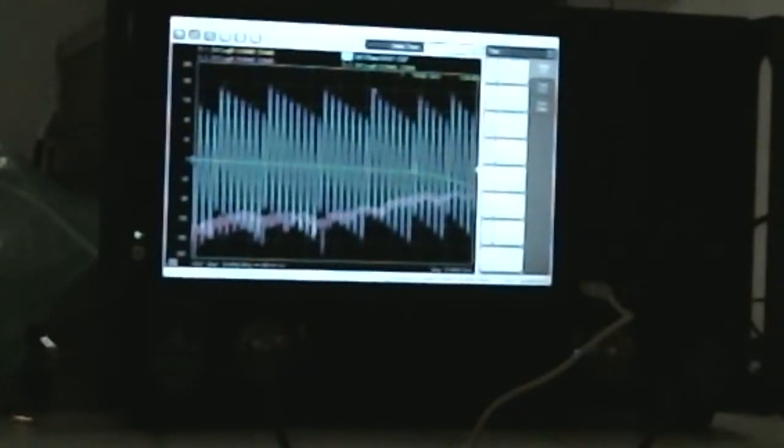But you need to make sure you're using really good cables, because you can get cheap cables from DigiKey and they're fine for some applications. But if you're working, like I said, anything above 1 gigahertz is where you really need to be careful. Okay. So for this cable, we can work till 3 gigahertz usage.